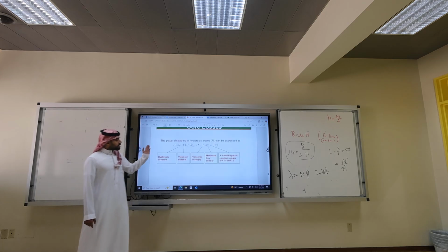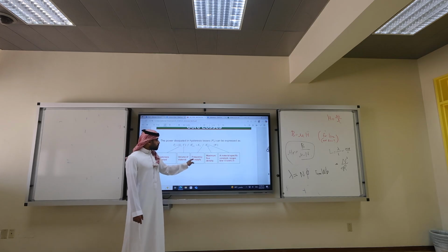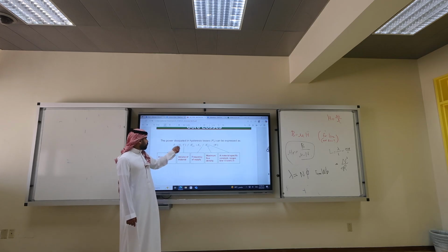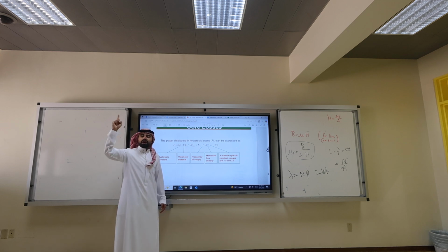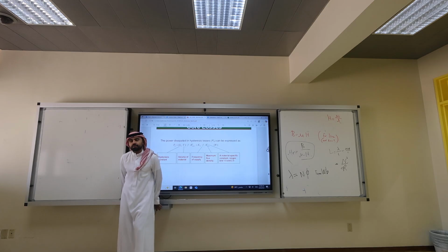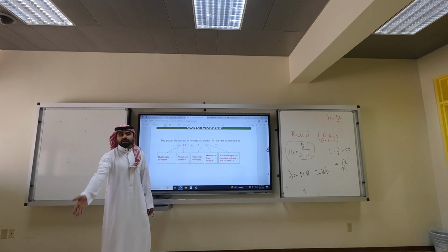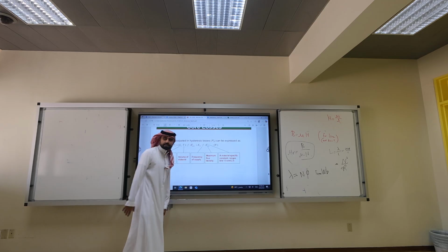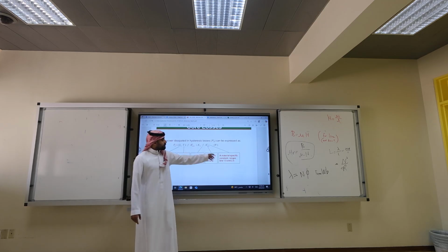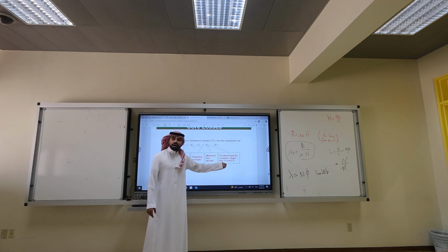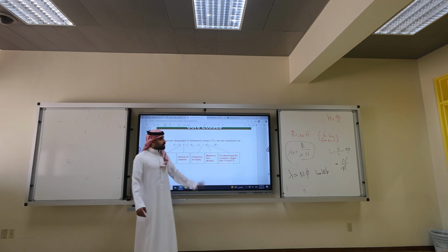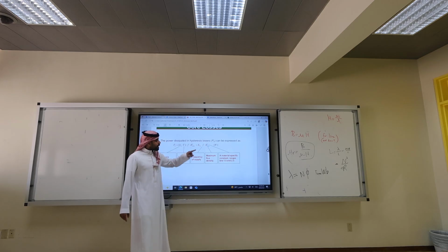Last information is the equation to calculate it. It's a constant called KH, which has to do with the volume and the hysteresis constant. Capital K or small k times the volume, times the frequency of power. So which one has more hysteresis, Saudi Arabia or Bahrain, for the same transformer? Saudi Arabia has more hysteresis, okay? So this is one of the advantages of the 50 Hz. You have lower hysteresis losses. But again, conservation of misery, we have bad things with the 50 Hz. Times the maximum flux with a constant n, which can be 1.5 to 2.5, an empirical formula. You're not required to memorize it, but if I give you a small problem, you can apply it, okay?